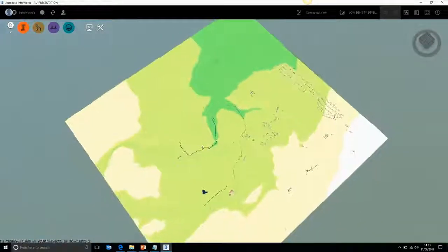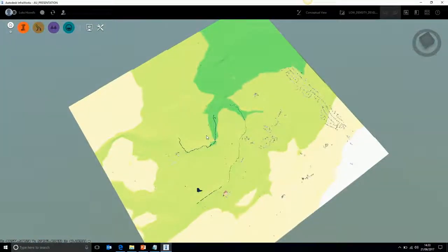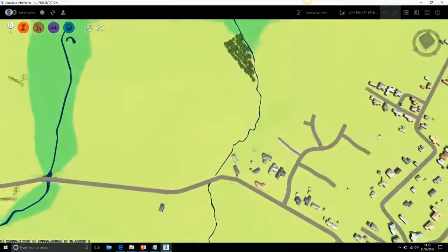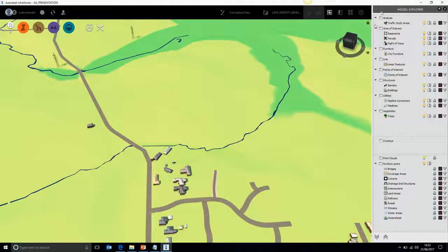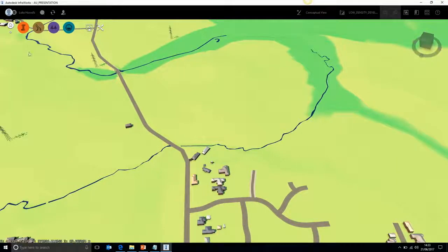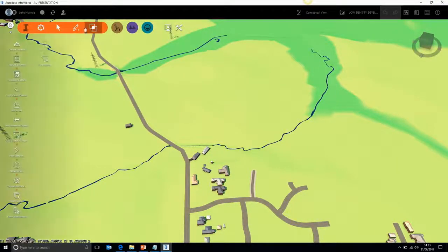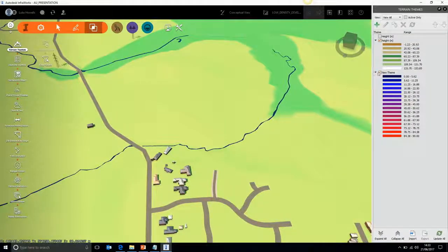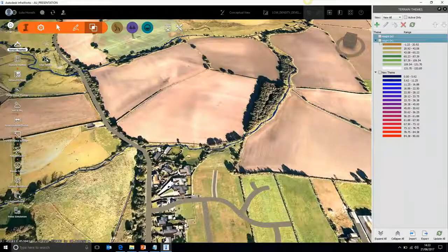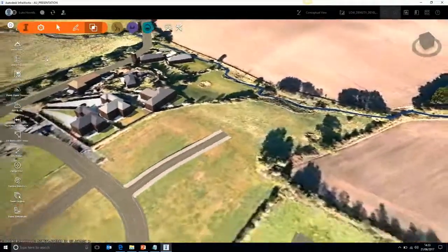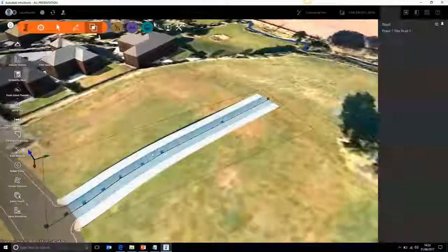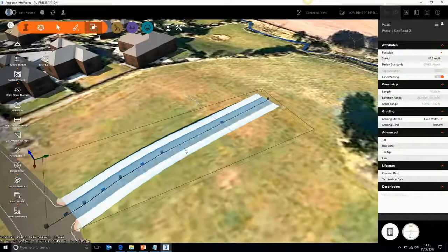Once we have the roads from our IMX in there, just while this is loading, we have the functionality to add all our drainage in. So, come into our site, let me just turn that display off. Just tick those off, don't need those showing at the second. As I was saying, now it's back to a component road. All the vertices are there for me to control. I can step it in if I wished.